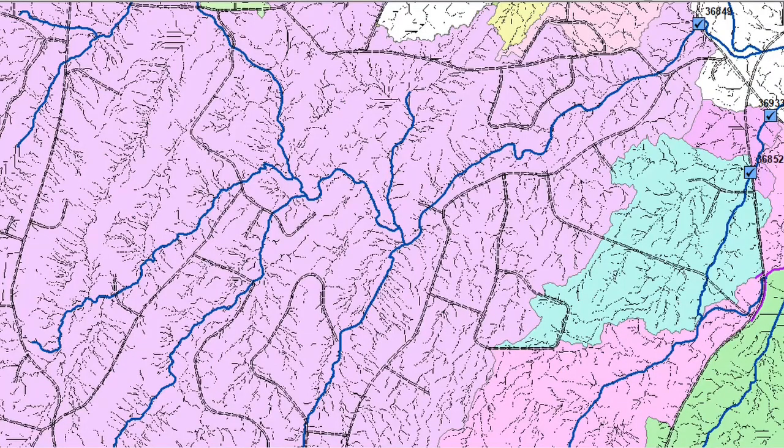So we talk about doing this editing process of adjusting the DEM, adding break lines, moving the points around, but how much editing do we really need to do? So here's an example. You can see there's a big watershed here in purple. We have county culverts in the upper right-hand corner. There's like 3 blue squares up there that represent county culverts.